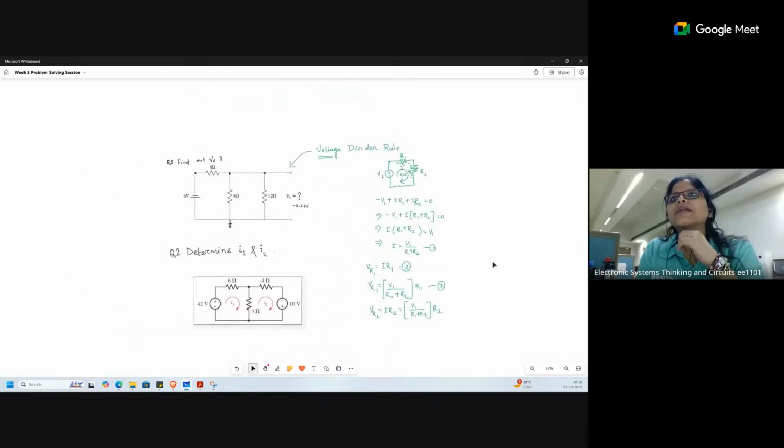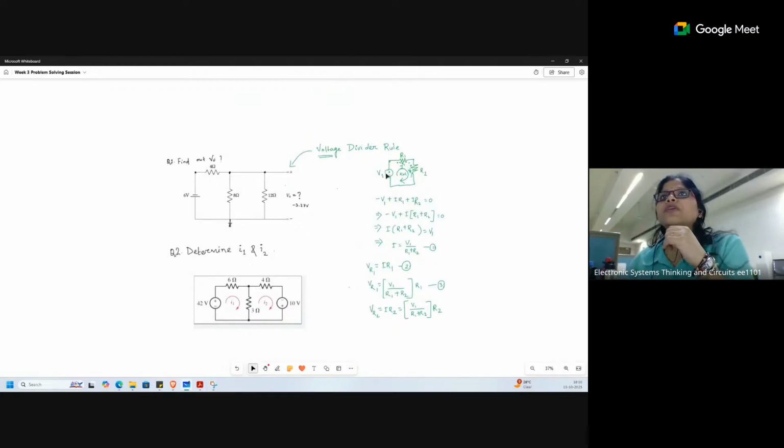I wanted to show the circuit and equation together. That's why I'm doing this. So you see here, this is the V1, right? And VR1 is the voltage across R1, VR2 is the voltage across R2. So now you are getting I equals V1 over R1 plus R2, which means total current flows in this series circuit. And we know that in the series circuit, total voltage gets divided among the resistors, as per our knowledge before, in the series and parallel circuit we have studied, right?